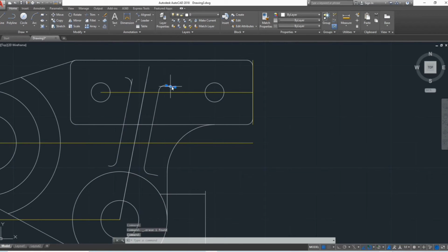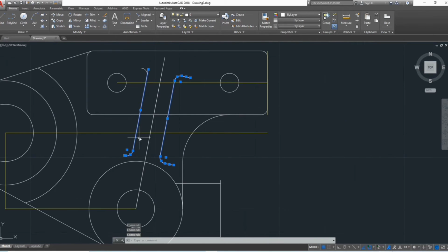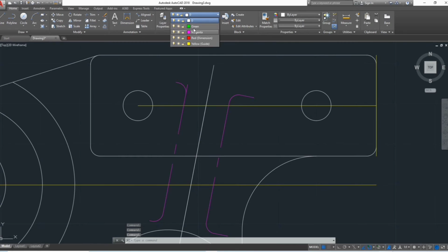Now let us change this into color green with the line type of dash line or the hidden line. Just click it all, the oblique line, and then change the color into green, and then trim this excess.